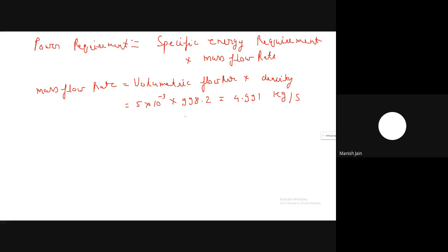The power requirement is 4.991 multiplied by the specific energy requirement, that is 153.93, and then divide by the efficiency of the pump.